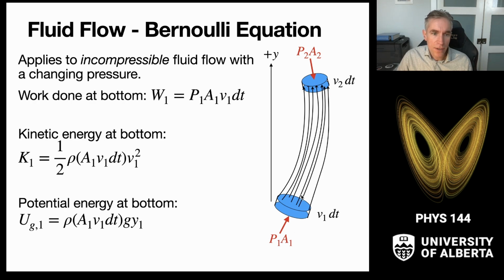And so that's basically going to be the distance. So this is essentially force, pressure times area, times displacement, v dt, and it describes how much work is done on the fluid from a pressure pushing upward on it, so sort of forcing it along the flow tube. And it travels along the flow tube up a little later, and we'll consider the top in a moment.